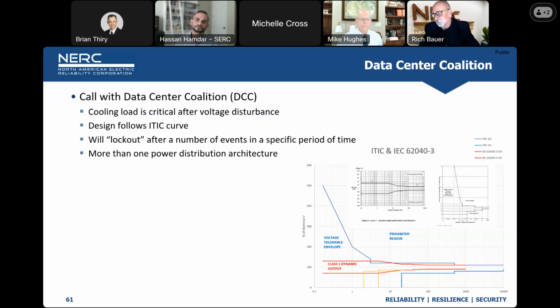And so at the end of the day, what we're concerned with is at what magnitude of load rejection causes a frequency that's high enough that could present reliability problems on the system, such as maybe widespread tripping of resources because we're in this very large over frequency condition.